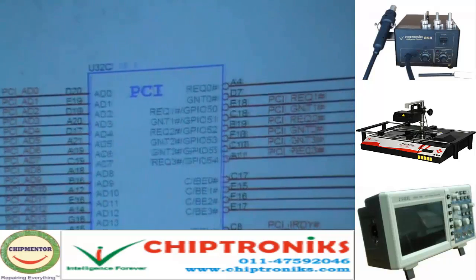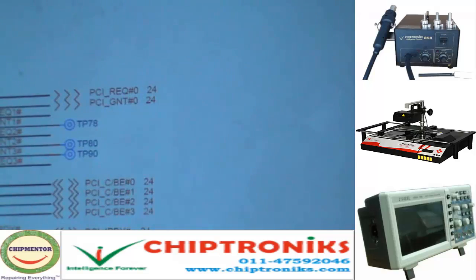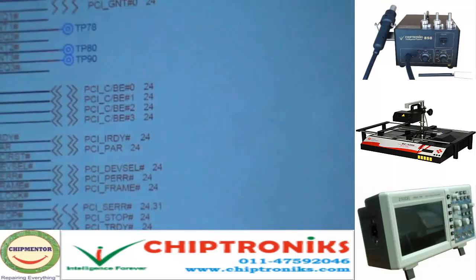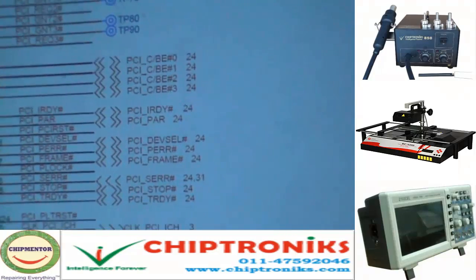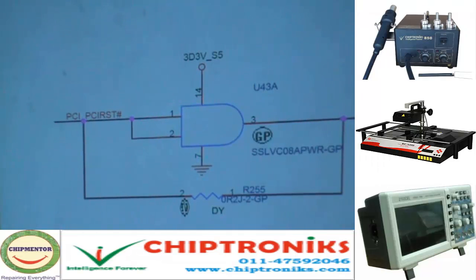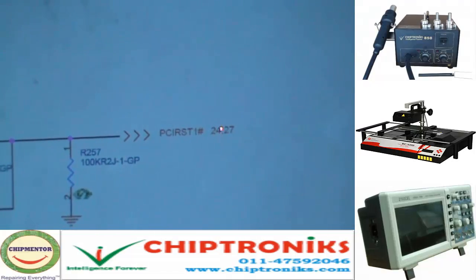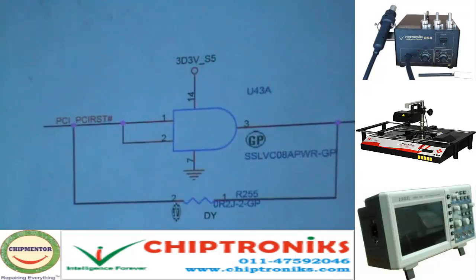On page number 18, we discussed that this portion represents the PCI connection. Here there are 2 important signals, PCI reset and PLT reset. We can measure these 2 signals over here. See U43A, PCI reset. Why is this IC there? In order to generate 3.3 voltage at this PCI reset. You can measure this PCI reset at pin number 22 of the mini connector, and similarly PLT reset.